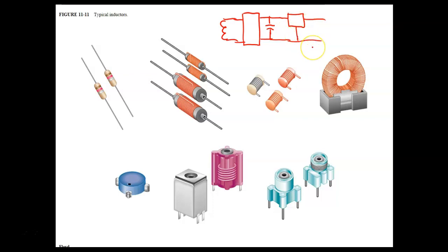Now these are the ones the trainer uses. I can show you the schematics on the trainer. This is what they use. Now these guys are extremely easy to fix. I mean, if you got a trainer where the power supplies are bad, it's real obvious on our trainers that the power supplies are bad, those LEDs on the side are either off or they're real dim.